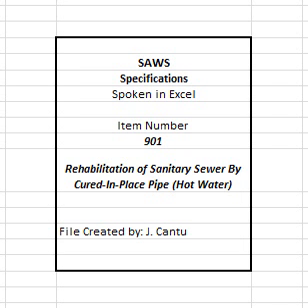Contractor's failure to account for oncoming weather will be contractor's sole responsibility, which may extend to removal of damaged or improperly cured CIPP resulting from interrupted CIPP construction process. H. Contractor shall notify owner 72 hours prior to liner wet out process for approval. Weather conditions and on-site conditions need to be considered. I. 1 hour prior to liner being installed, contractor must televise host pipe with inspector present to ensure no pipe condition changes have occurred.